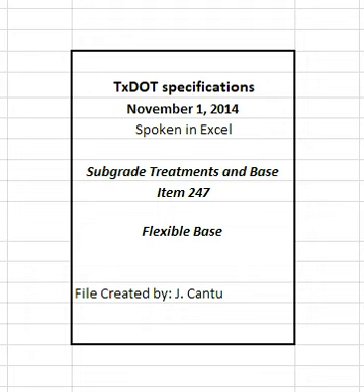4.3.2 Density control. Compact to at least 100% of the maximum dry density determined by TX 113E, unless otherwise shown on the plans. Maintain moisture during compaction within plus or minus 2 percentage points of the optimum moisture content as determined by TX 113E. Measure the moisture content of the material in accordance with TX 115E or TX 103E during compaction daily and report the results the same day to the engineer, unless otherwise shown on the plans or directed. Do not achieve density by drying the material after compaction.